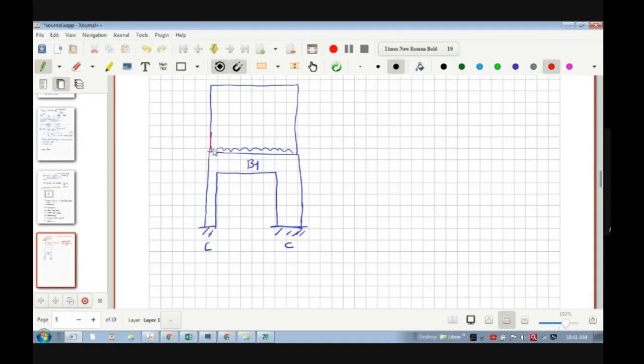As it is a weaker column, the bending moment on the weaker side is less. All of you know this. And as it is a deep column over here in this direction, it will attract more moment. So it may be something like this. Smaller moment here, and this moment will transfer into the column. Bending moment, and this also will transfer to the column. There is no problem.